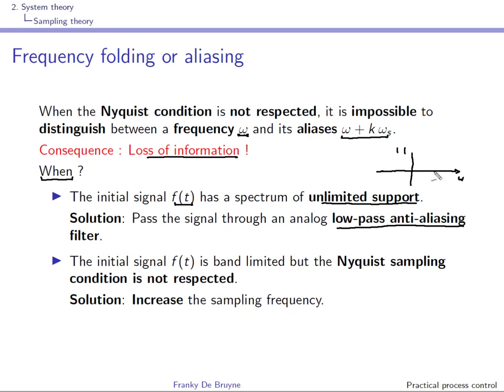It will look like this, and you will have to give it a sufficient roll-off. If the roll-off is not sufficient, you'll have to put the cutoff frequency of the filter a little bit earlier than the Nyquist frequency, so that you have a sufficient attenuation at the Nyquist frequency.